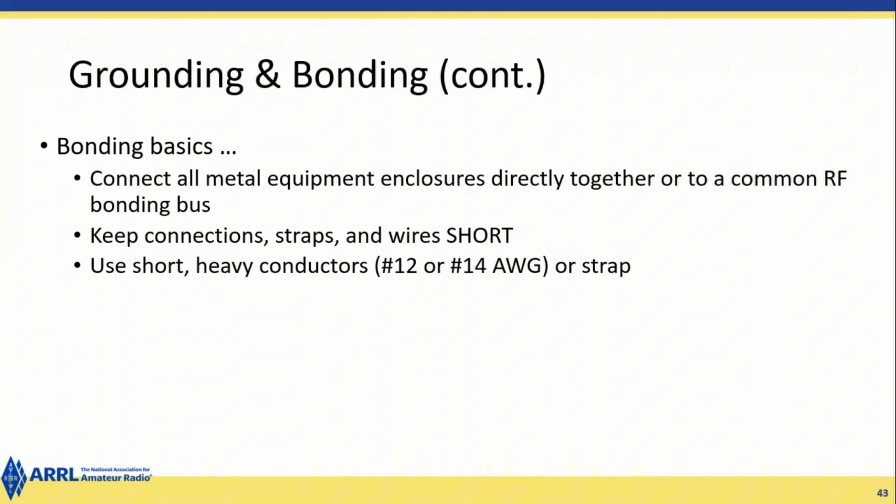Which of the following might be used in reducing RF interference to audio frequency devices? Bypass capacitor. Which of the following could be a cause of interference covering a wide range of frequencies? Let's see, arcing power electrical connection. C. What sound is heard from an audio device experiencing RF interference from a single sideband phone transmitter?